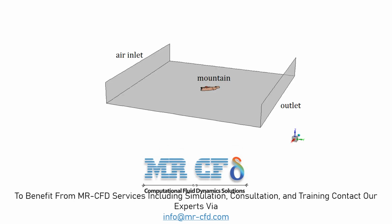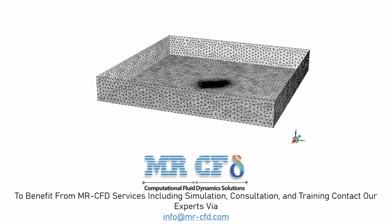The geometry of this model is designed in ANSYS Design Modeler software and consists of an airflow inlet, the mountain itself, and 3 different pressure outlets, including top and side walls and the main outlet. The model of the present project is meshed in ANSYS meshing software, and the mesh type used for this geometry is unstructured, and the element number is equal to 1,250,044.